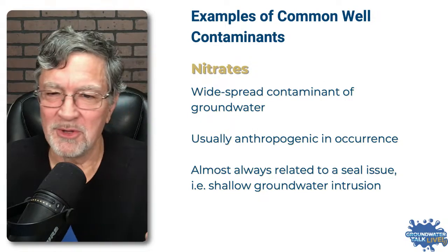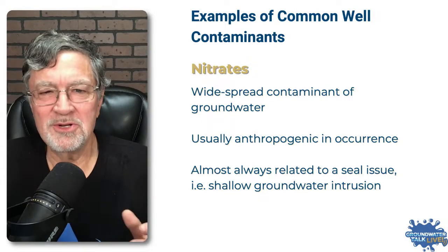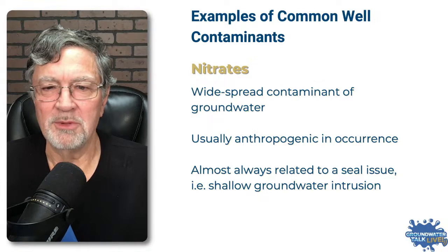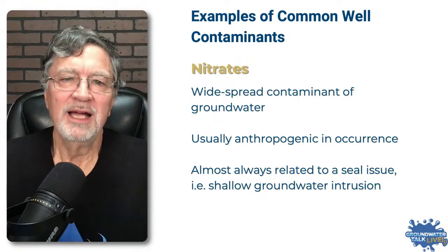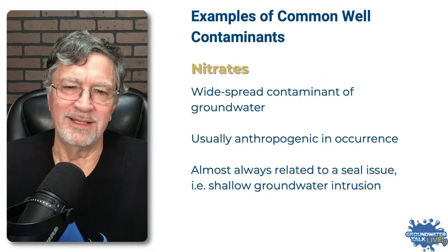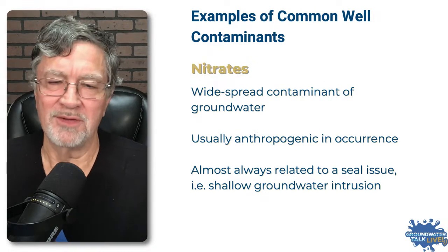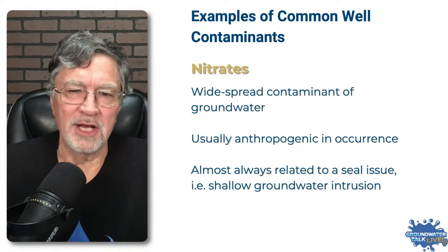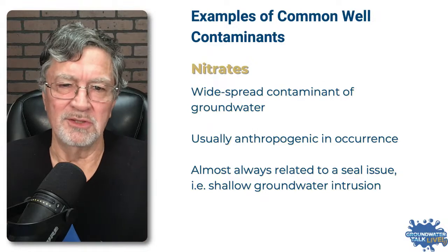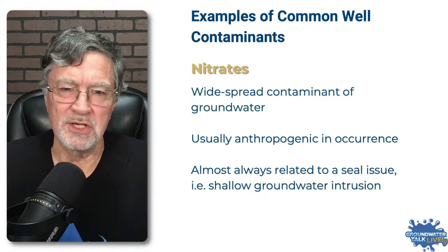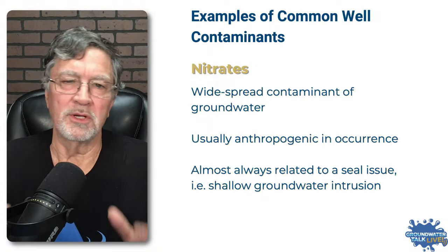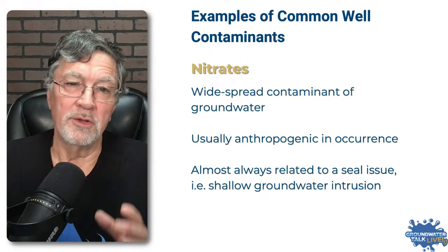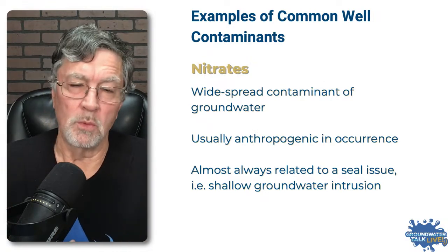That's a topic for another day also, but usually nitrates is going to be a shallow groundwater issue, and I would say that well over 90% of the situations that I deal with nitrates in, it's going to be a seal issue. There's going to be an inadequate seal or a degraded seal that's going to allow shallow groundwater that's impacted with nitrates into the well.